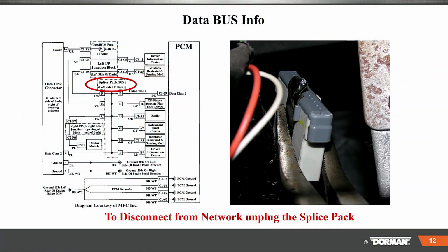So here, again, we can use different jumpers to find out where it is. And obviously, when you jump the one, I'm going to say like the radio is bad. Okay, so now you take the radio off the bus, put the comb back in, right? Here's our comb. Plug the comb in. Now everything else is working and the bus is working fine. You're going to need to take care of that radio or infotainment center.